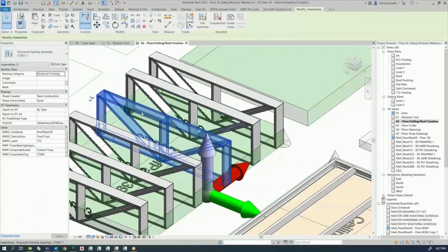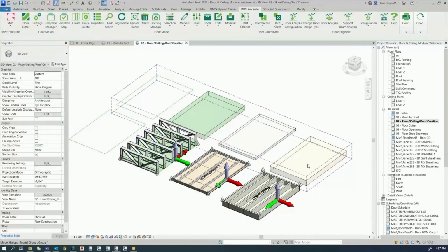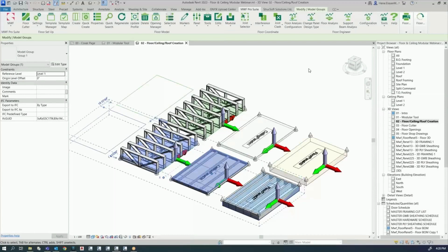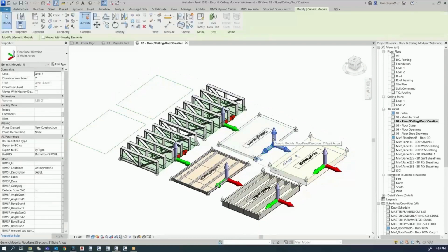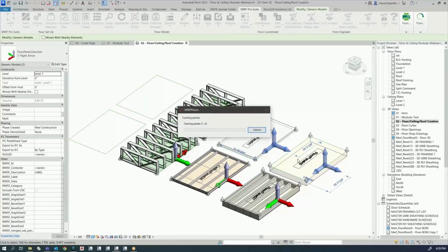here you'll notice that we have assemblies because we created a wall truss. Okay, so let's try this. So now we can try the tool. We'll make a selection, go to modular, copy members on all identical groups. Okay. So here what happened is we just have to regenerate. It did apply the panel, but it didn't show the framing. This could happen. It's okay.